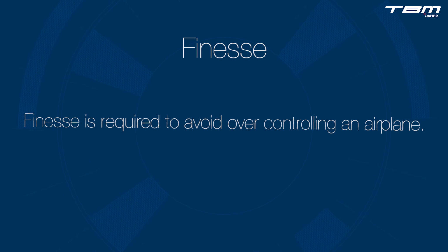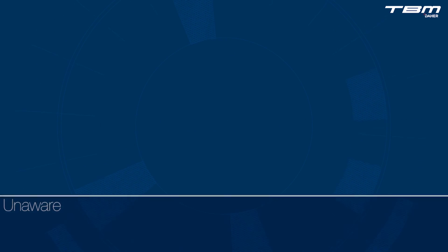If not managing the rudder properly, abrupt applications of either the flight controls and/or power when flying at the edge of the envelope could pitch, roll, or yaw an airplane forcefully enough to induce and aggravate a stall. Having viewed this video in its entirety, you are now aware.